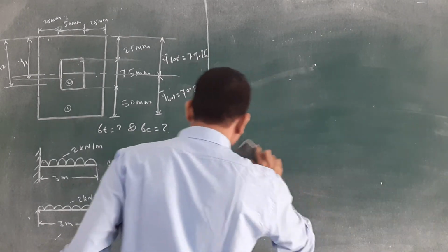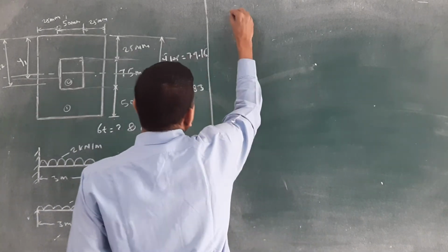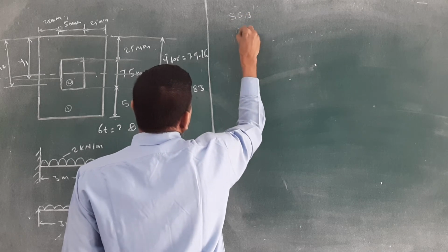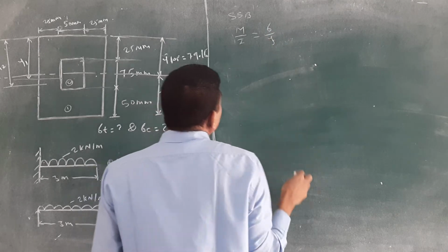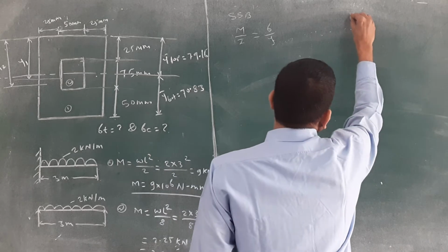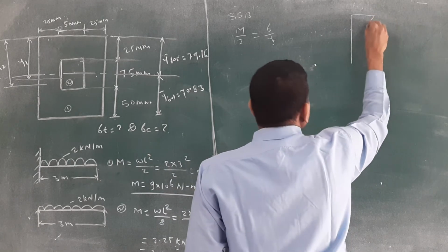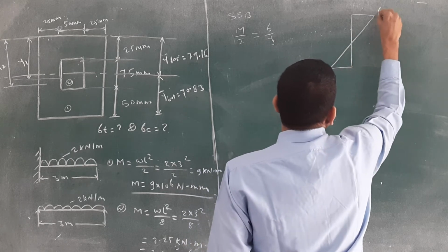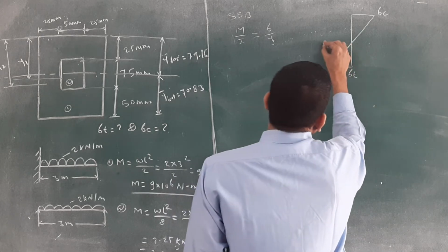Yes, all of you getting? Yes, good. Then simply supported beam, SSB, I will write. Simply supported beam, you know that generalized formula, M by I is equal to sigma by y. For the simply supported beam, what is the nature of bending stress distribution diagram? We have seen above the neutral axis, you will get which value? Yes, sigma c is there, and below the neutral axis you will get the sigma t.